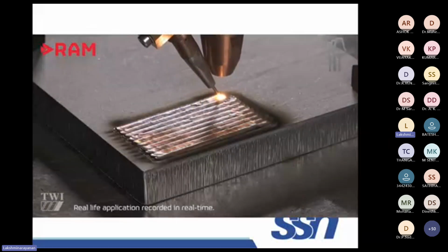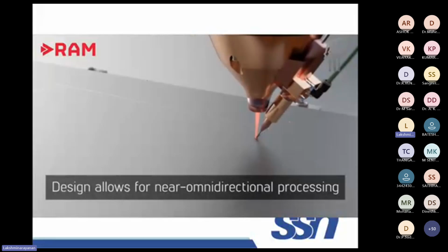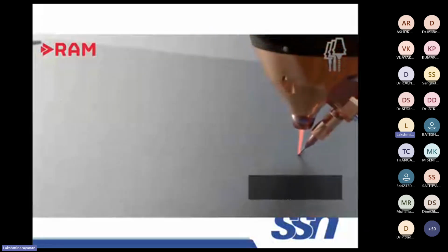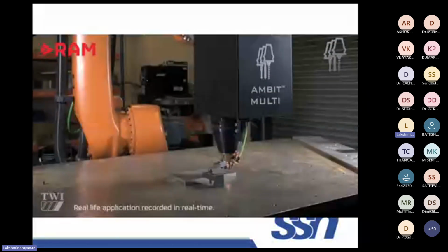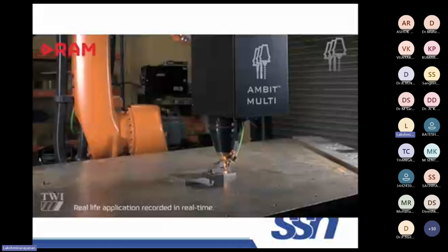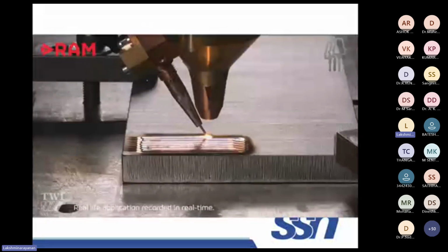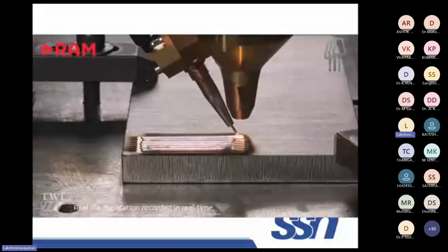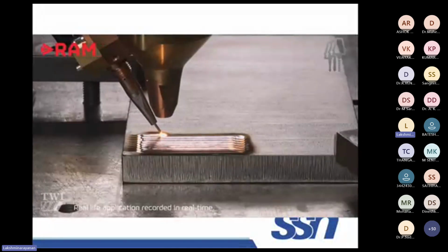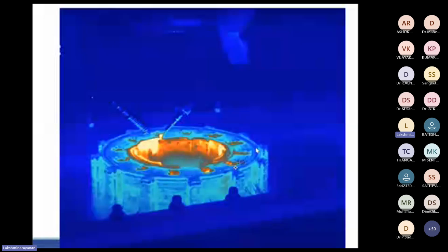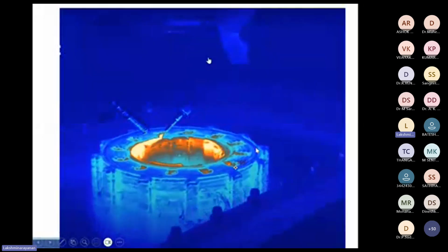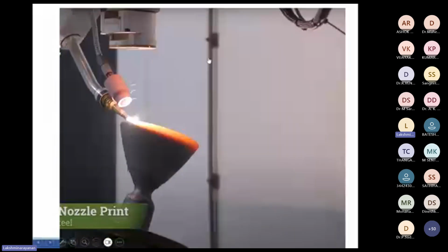This additive manufacturing is also nowadays popular for cladding purposes, where you want to protect the substrate. Suppose you take mild steel and don't want corrosion to dominate, I can deposit a thin stainless steel layer on that. This is very popular, earlier also it was popular. Now you can build functionally graded material on that. So this is one method, and this is another video where directed energy deposition is used.